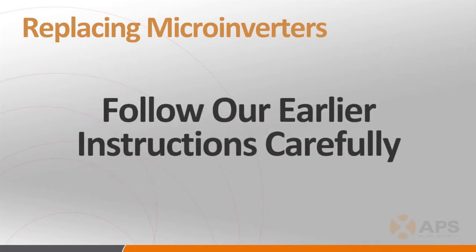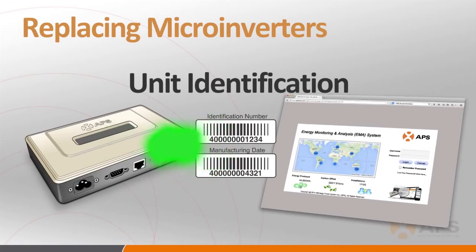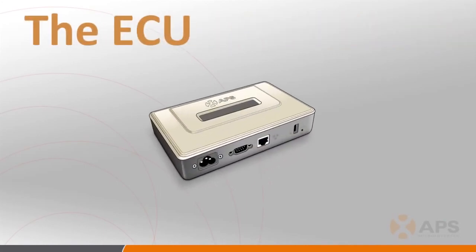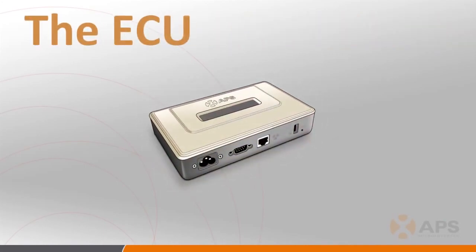Follow the installation procedures we've gone over earlier in this presentation to install the replacement inverter, making sure to change the inverter UIDs in the ECU and EMA to reflect the changes you've made. A few quick words about installing the ECU before finishing this training module.